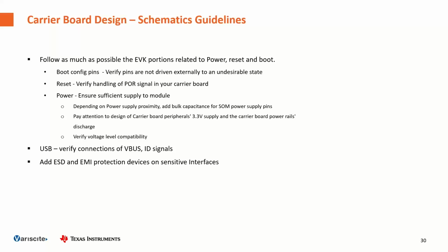There are pins that may be provided in the 1.8 volt domain, other pins that may be provided in the 3.3 volt domain. This is detailed in the datasheet. And if not declared differently, usually we refer to the 3.3 volt domain. But when some configuration may change this to 1.8, we write this in the SOM datasheet. Just be careful.